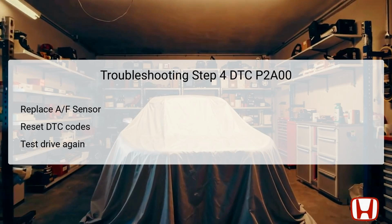It is essential to use a genuine or high-quality replacement sensor suitable for the Honda Civic 2022 Plus. Once the new sensor is installed, clear any diagnostic trouble codes stored in the PCM. This procedure ensures that any leftover codes from the previous sensor do not interfere with the new sensor's operation.